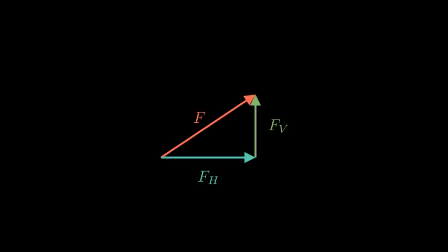We break the complex curved force into a horizontal shove and a vertical weight. First, let's look at the horizontal force, Fh. Imagine you are looking at the curve from the side, through the eyes of a fish. To the water, this curve feels exactly like a flat vertical wall of the same height. So, we use our standard formula, ρ g h_c A.